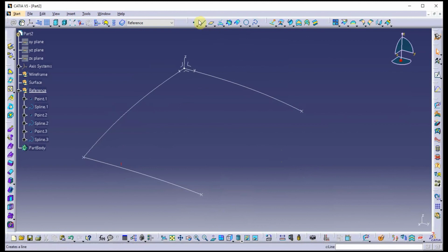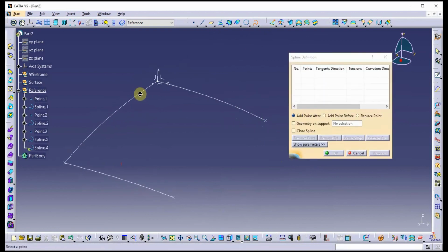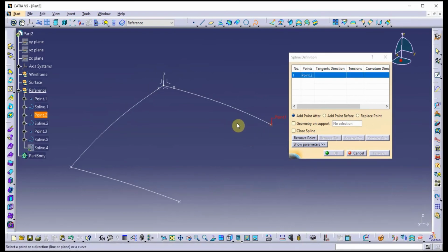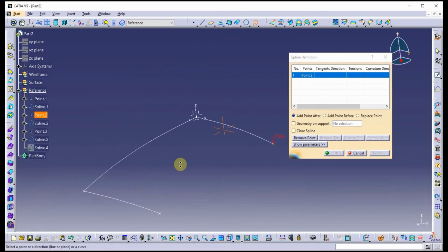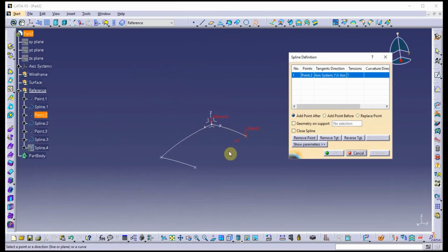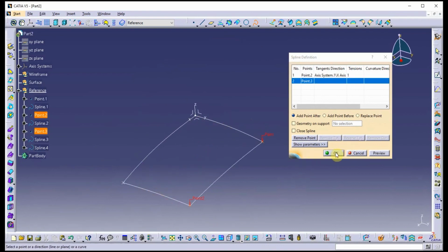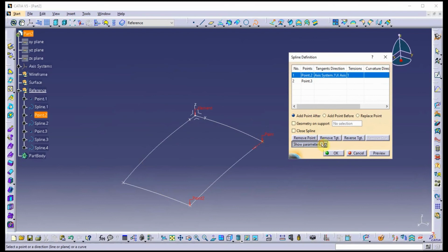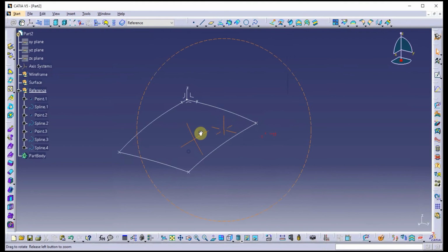And then finally for this one, not as important for mirroring over the seam, but I'm still going to be intentional with my continuity, so I'm going to make up something here. Let's say that it's going to the y-axis, if I can select that here. Okay, and then to this point. And let me set that to be G2. Okay, fine. Now, I've got my curves in.